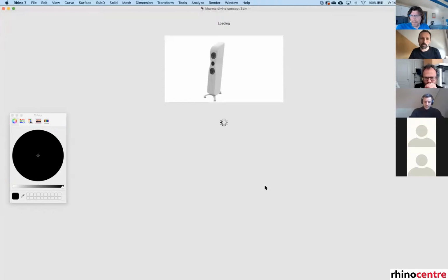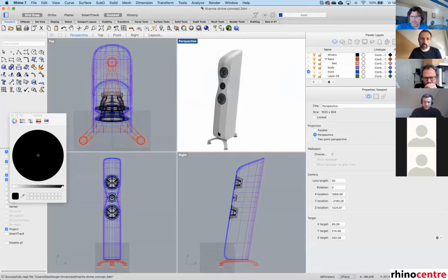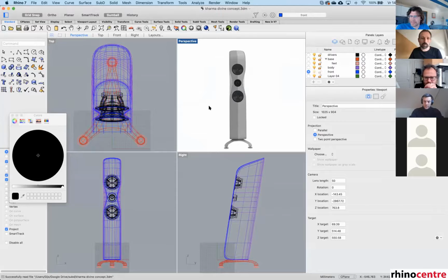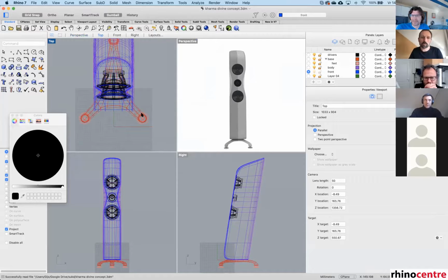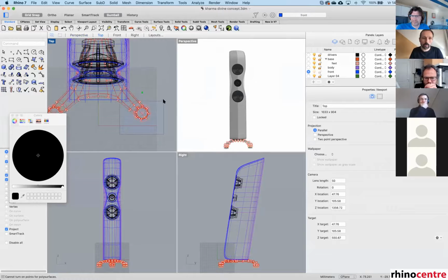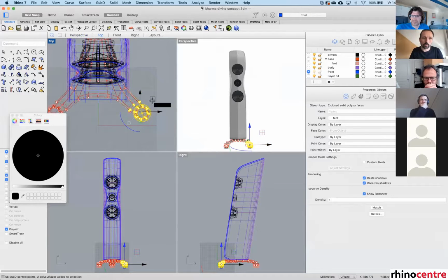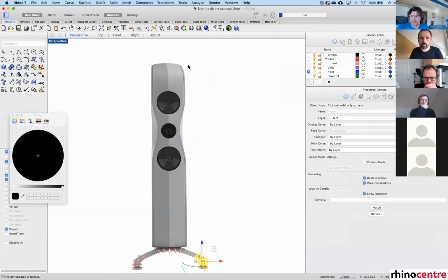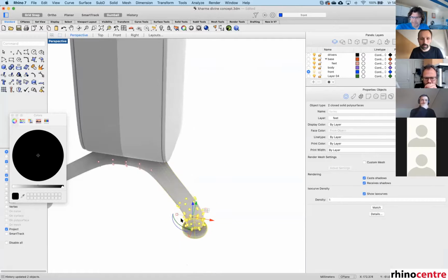I will show another thing I was working on, and that is this concept, and a good example of what you just mentioned. If you want to do some changes, for example, if this needs to be just a little bit longer, in Nurbs it's going to be difficult, and in Subdivision Surfaces it's a matter of turning on control points and starting to move those out or up or down.